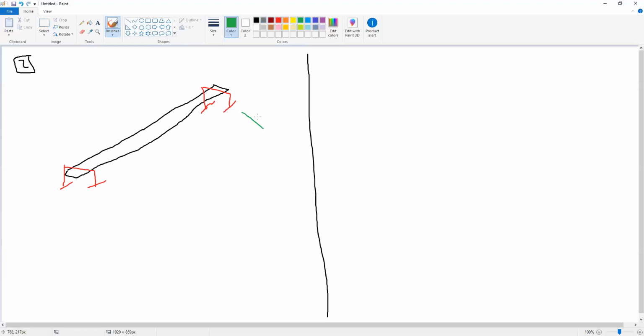The span, again, you should set up the span to be L equal to 900 millimeter. And we expect that the maximum deflection will be in the middle of the beam. So this is our dial gauge here, and we need to re-zero it each time. This dial gauge is located here at L divided by 2.